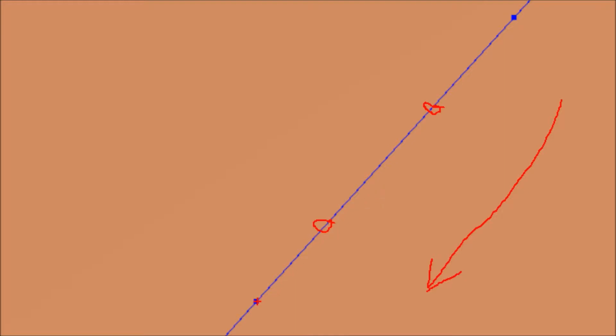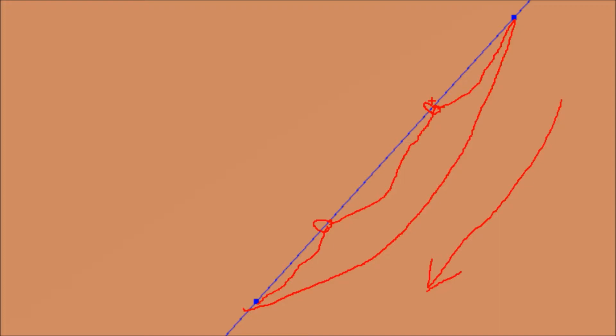Even though the actual path is not straight between points, compared to if you just have 2 points, if you have more points, the tool can cut closer and more accurate to the surface, and the result will be, of course, much smoother and better.